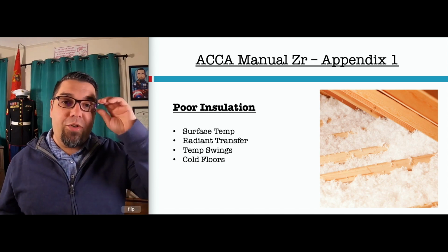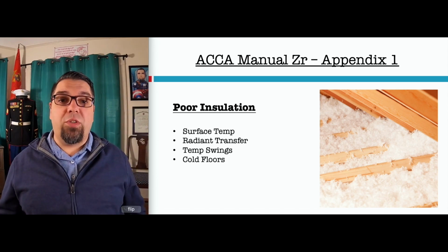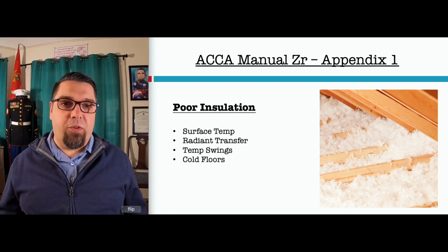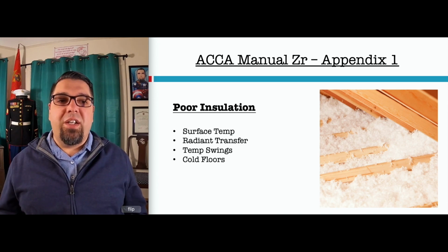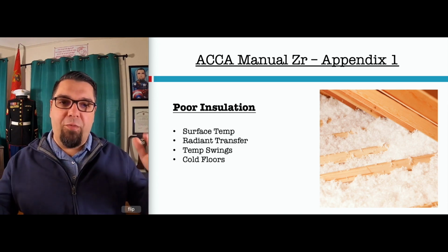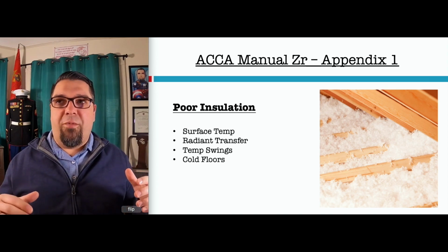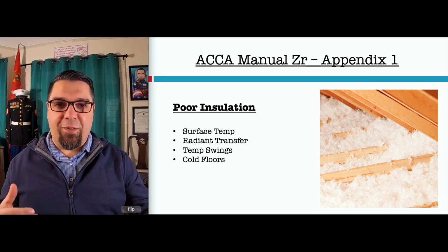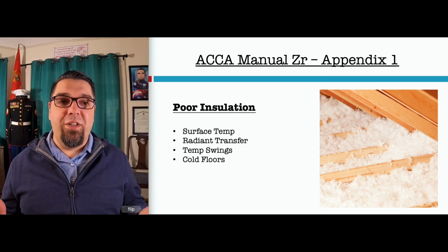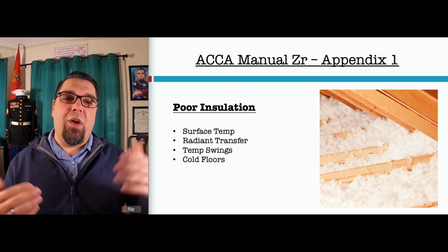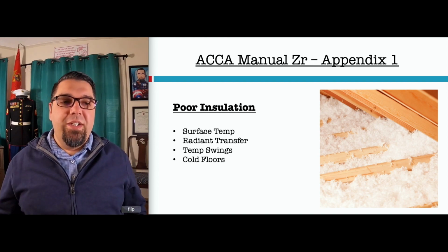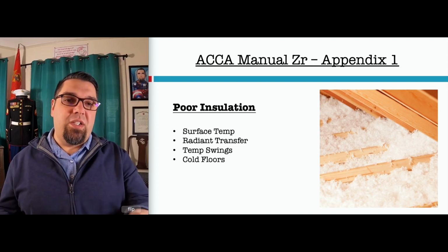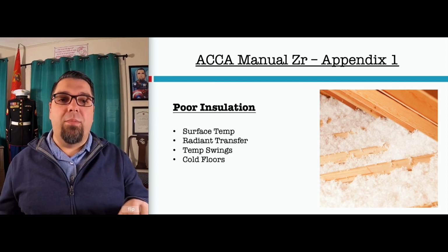And trust me, at my house, it's an old Victorian. We've done a lot of work when it comes to air sealing and insulation just to try to feel comfortable in some of our rooms. Newer construction is probably a little less of a concern because you're at a very minimal amount of difference. If I was to add insulation, it's not going to make a big difference because the code when that was constructed already required, let's say, R18 or R30 or R32 or whatever it is upstairs. So depending on the age of the house, this can make a bigger impact when it comes to comfort and temperature swings.